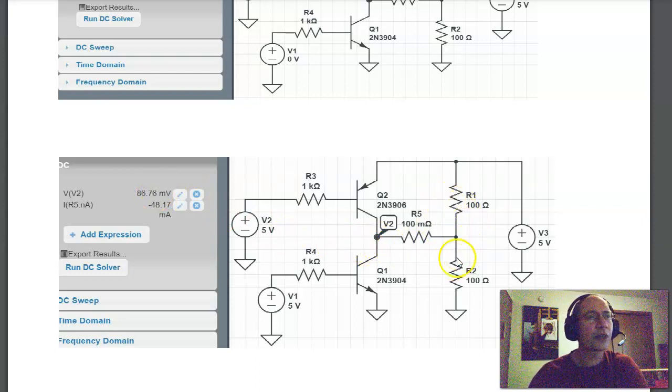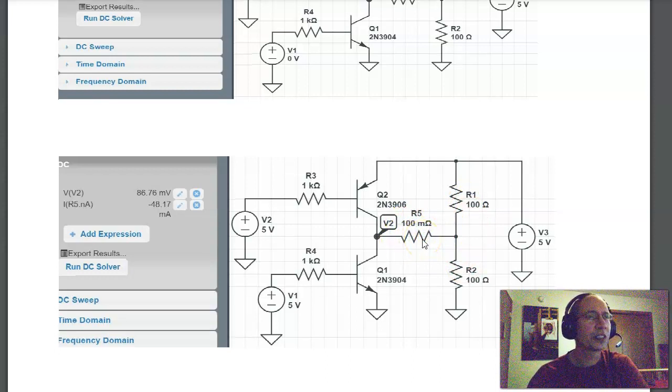And over here, I build a 2.5 volt source with 50 ohms. That's the Thevenin equivalent of the 200 ohm resistors. Again, the Thevenin voltage is half of that, 2.5 volts. Thevenin resistance is 100 in parallel with 100, 50 ohms. R5 is just to let me measure current, something small, just as a test resistor.